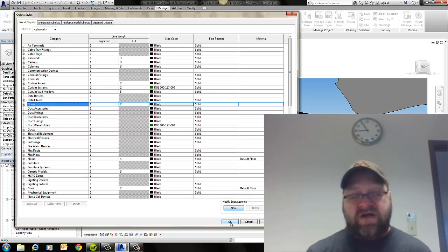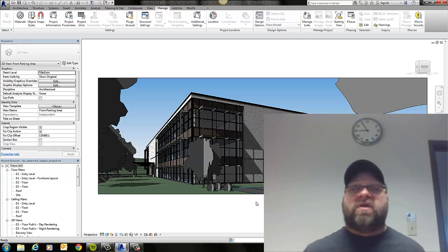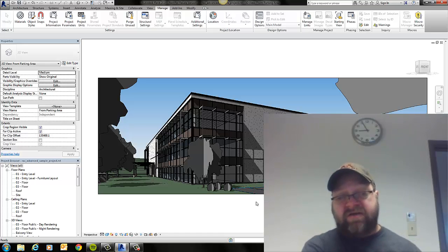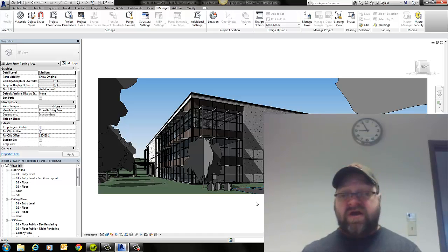And another bigger downside is that I have no way of really organizing things that don't have any kind of logical connection to each other. When I'm working with layers, sometimes I can put a bunch of stuff onto the existing layer, right? I could put walls, doors, windows, fixtures, and all that onto a layer called existing. Then I could put walls, windows, doors, fixtures that I'm tearing out onto a layer called demolition, and define just those two layers to look a certain way, because I want all those objects, whether they're windows, doors, or whatever, to all look the same.